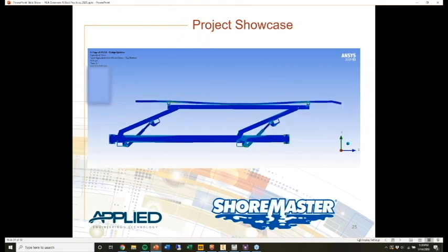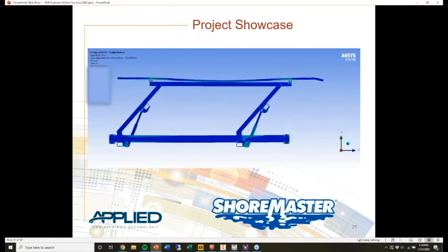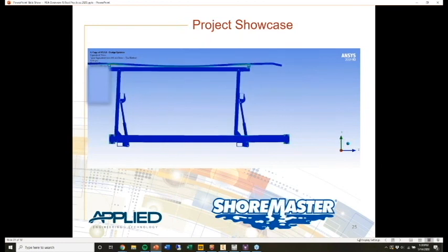So this particular simulation had 6 or 7 different weldments that we had to build in the finite element modeling environment. And then we have several joints, several connections. There's quite a bit of frictionless contact that we use in this, and quite a few joints to define all the degrees of freedom throughout the model. So a fairly complicated model of basically the whole machine that is the lift.